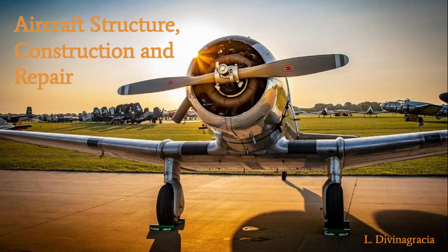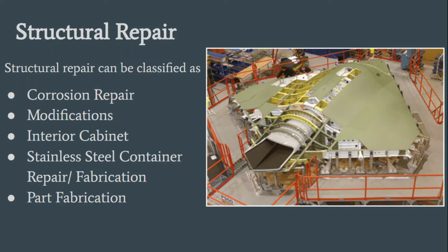Aircraft structure, construction, and repair 2. The repairs discussed in this chapter are typical of those used in aircraft maintenance and are included to introduce some of the operations involved. Structural repair can be classified as corrosion repair, modifications, interior cabinet, stainless steel container repair fabrication, and part fabrication. Damage to metal aircraft structures is often caused by corrosion, erosion, normal stress, and accidents and mishaps.